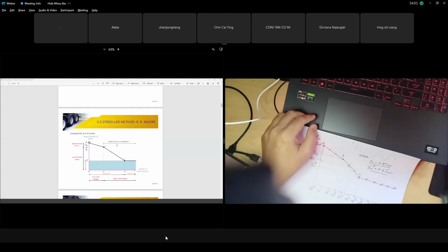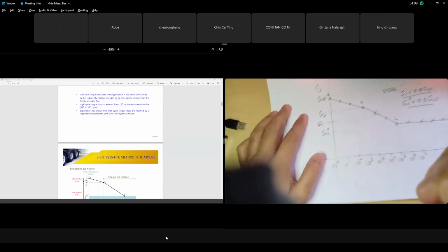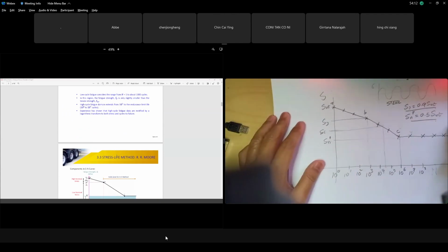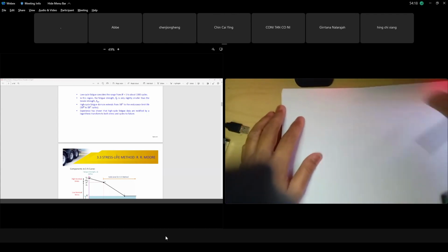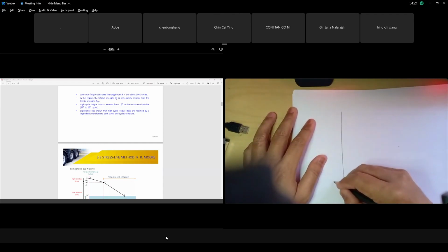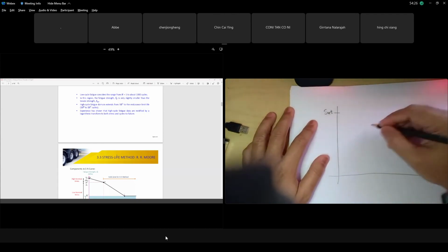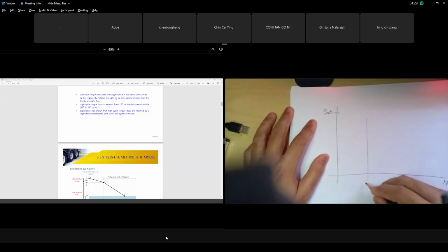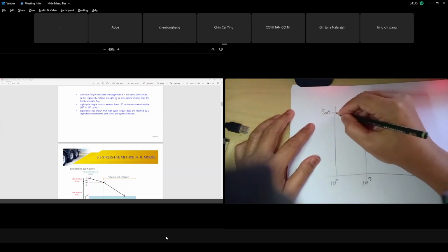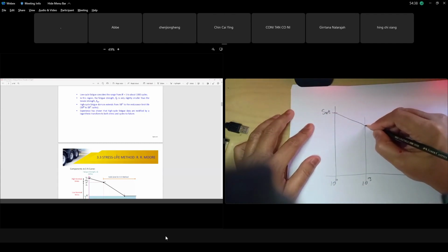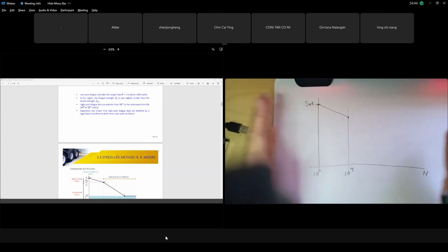This graph explains what finite life is. If you look at my sketch, I draw the graph again. This is your SN curve. This is the SUT of your material, and we have 10 to the power of 3 here. This one, 10 to the power of 0, is one cycle. You have a line. For your case analysis, you use your SUT. You plot the log 10 graph.